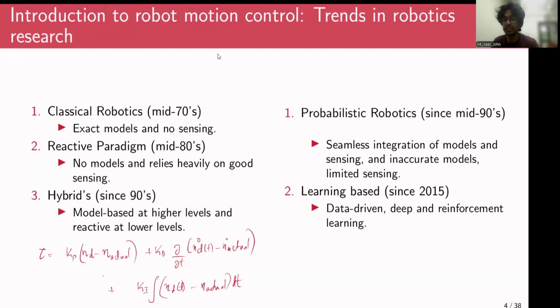If the error is increasing fast, the derivative gain would increase, and if the error is decreasing very fast, the derivative gain would also kick in to anticipate further future changes in the error. So here, as you can see, we are purely relying on feedback, right? Desired would be a feed forward term.